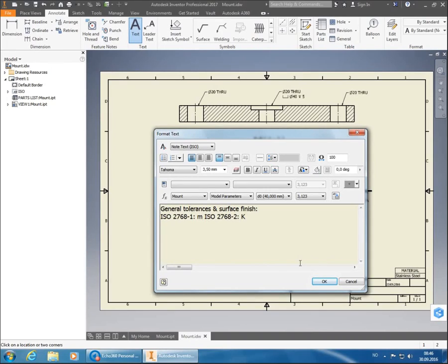So if you're ever wondering what to put, for an example, on this submission, a lot of these submissions had just figured out that they wouldn't put anything in there since it didn't say anything about general tolerances in the task itself. But you should always put them in. So I've written on most of them that it would be nice to see the general tolerances. And if you are unsure on what to put there, it is always nice to use the medium one. That's just my general tip for you.